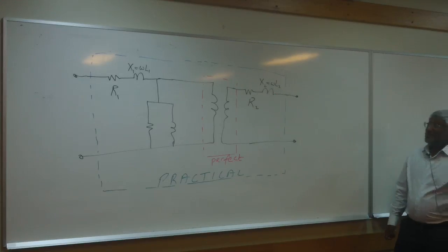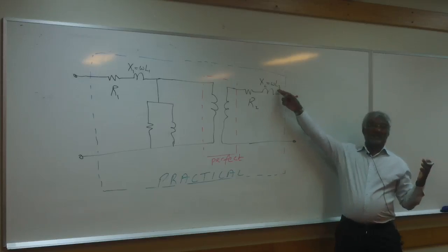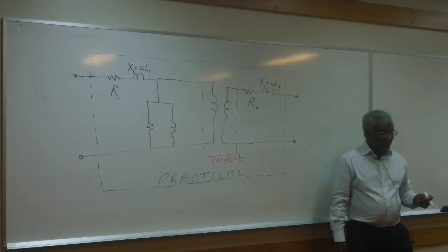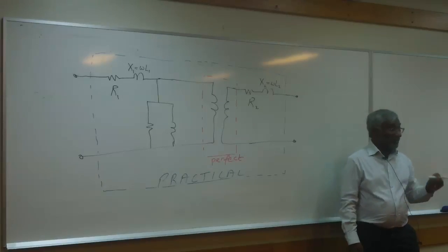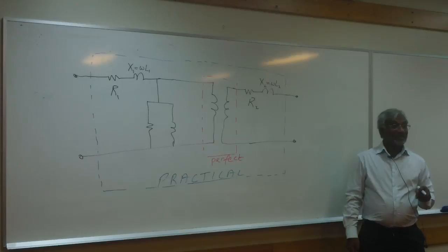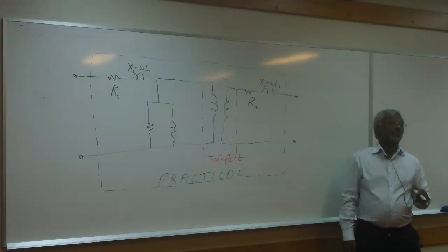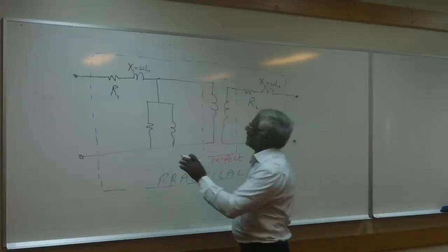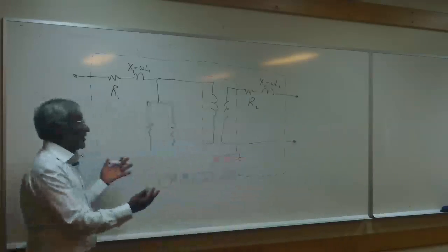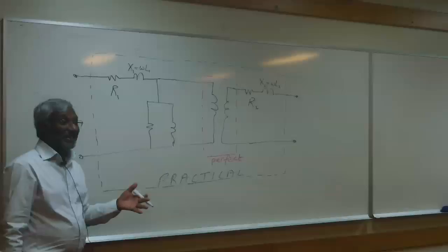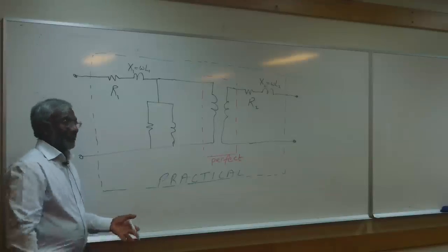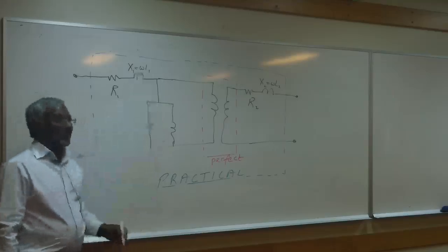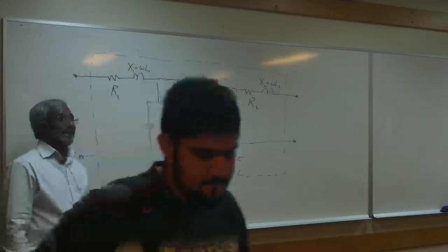Now, as I say, the picture in your mind should be where is this flux? If I give you a transformer, I put it in front of you, and I say, where is the leakage flux? You have to be able to point to the path of that leakage flux. If you cannot, well, might as well go home and watch TV. I am serious about this. If you are a power engineer, you have to be able to show me where the leakage flux is in the physical transformer.